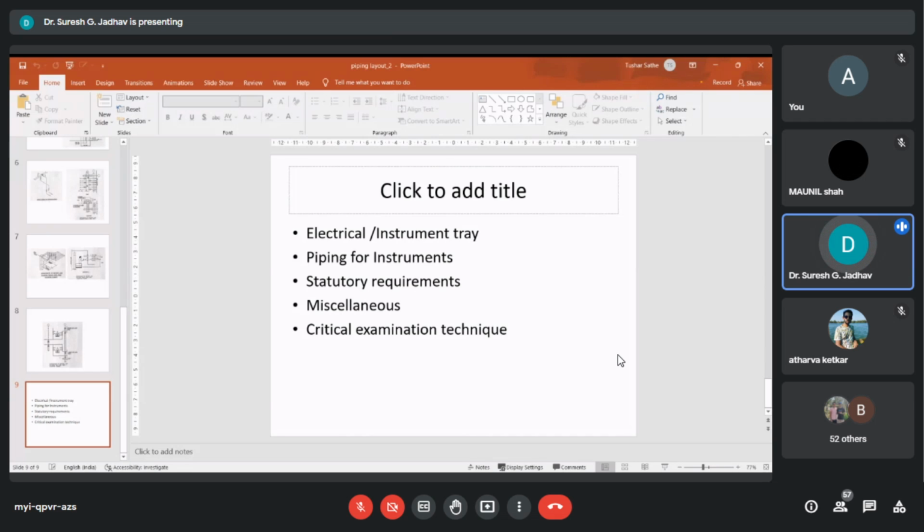finalizing the structural levels. Generally, the lines that connect two lines located at a level higher than the top tier should run on the top tier of the rack. Lines having one end located at an elevation lower than the bottom tier can run in the top or bottom tiers. If both ends of a line are lower than the bottom tier, the line should run on the bottom tier of the rack. The elevation of lines can be influenced by the valve and instrument locations in piping instruments.